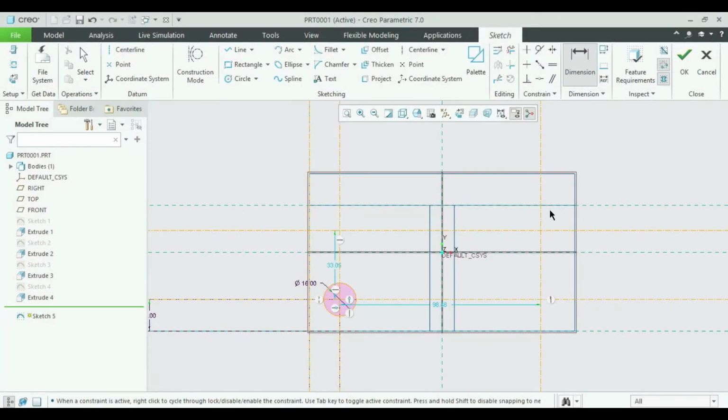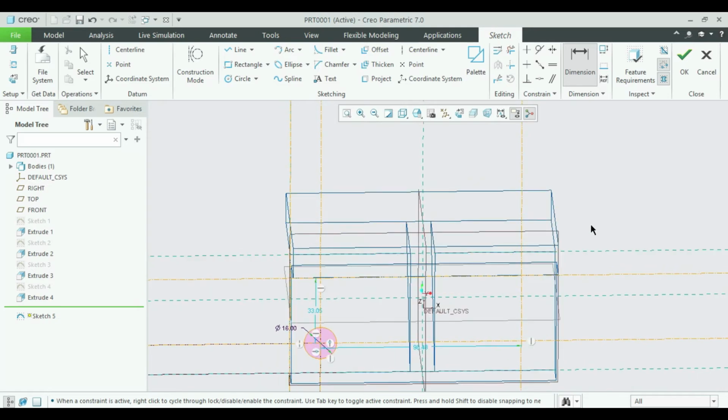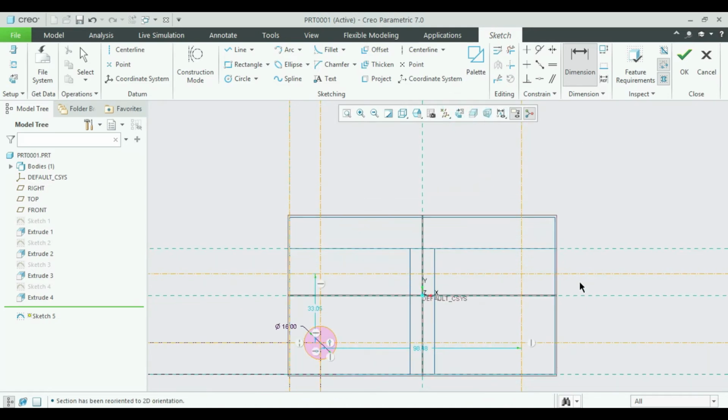I'm sorry for this inconvenience. Okay, now dimension is done. We just have to press only once on the type of the dimension top and press the middle button. It shows you automatically. Yes, now you can see here 15, give it 15. One more is here in the dimensions, 15.